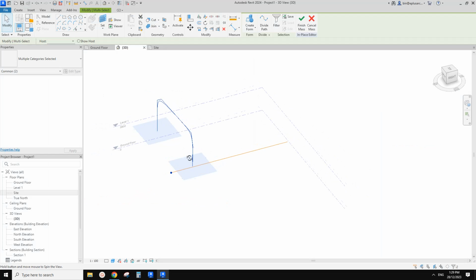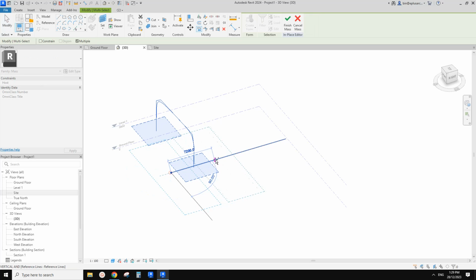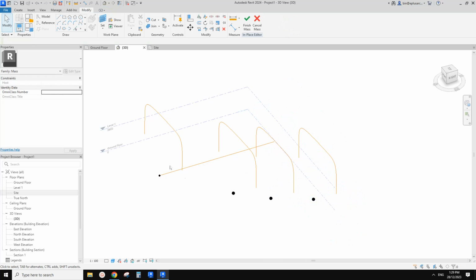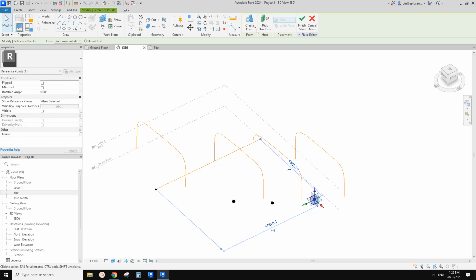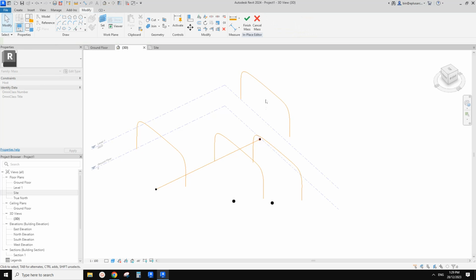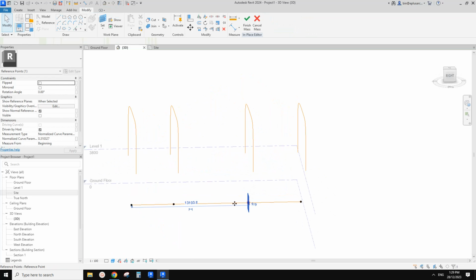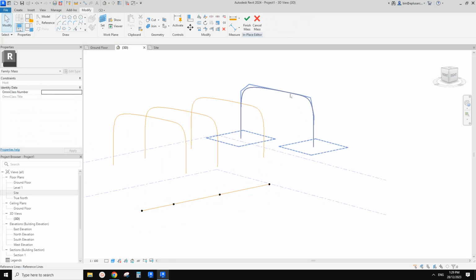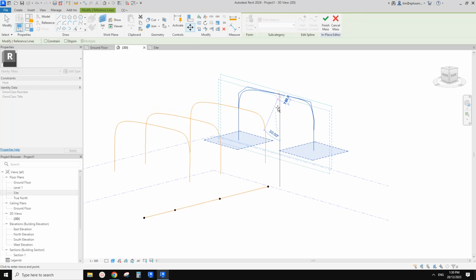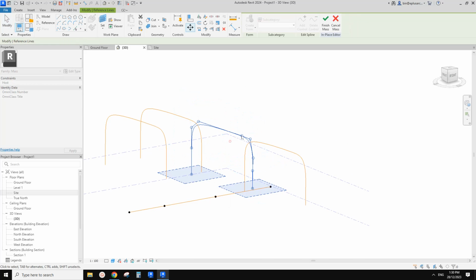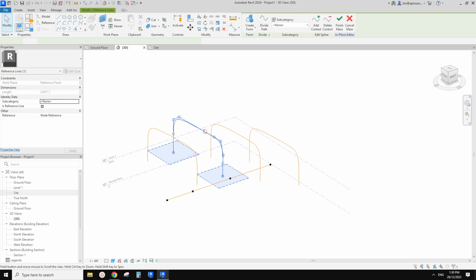Okay, so let's just copy this. Copy this spline together with this point, and let's just place it roughly here for now. One, two, three, maybe four altogether. Then we just pick new host. I'll just place it on this end, place another one roughly here, place this one roughly here. You can always adjust the point and move. You can use MV, move this down a little bit, so we can, yeah, I think that's it.